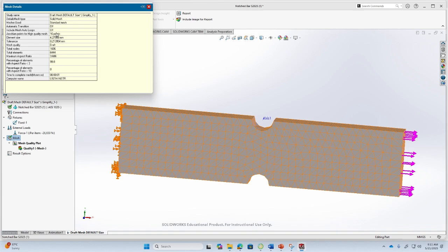Now what does that mean? Basically that means that, like I said, in SolidWorks, I can draw it for you on the board. So when you are going to have these elements, right? So let's say this is one of those wedge type elements. So you've got all of these nodes. So the minimum computation that the software needs to do is on each one of these nodes, right? But then for high quality, you can have more nodes somewhere here, for example, mid-side nodes we call them, right, on each of those faces. So it can be here, here, underneath here, or you can even have nodes over here for quadratic elements.